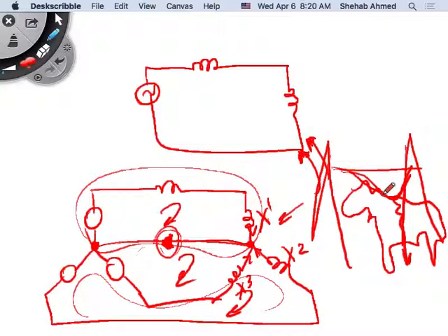But this is a single phase to ground fault, right? One of the phases touched an impedance, and this impedance is connected to ground. So it's not, for example, a pure bolted short circuit. We call it a bolted short circuit when it's solidly connected to ground through no impedance, basically. So what we will find is that symmetrical components theory allows us to get a feeling of what's happening in the system as well. Okay, so it allows us to solve the system easier.